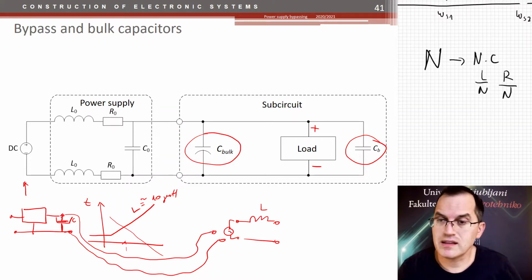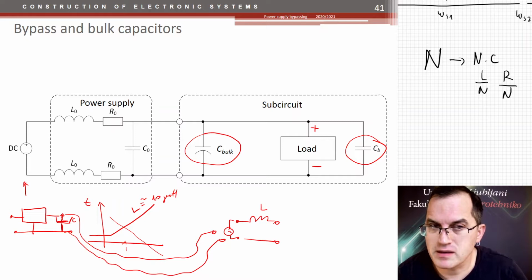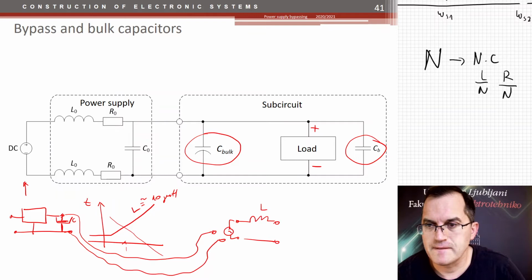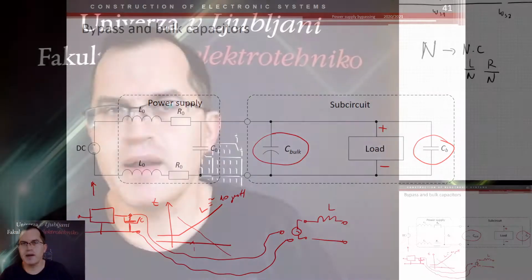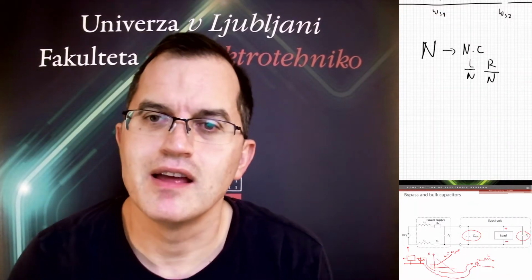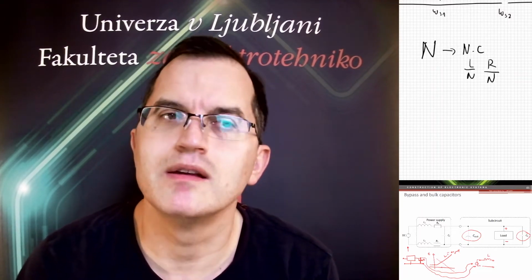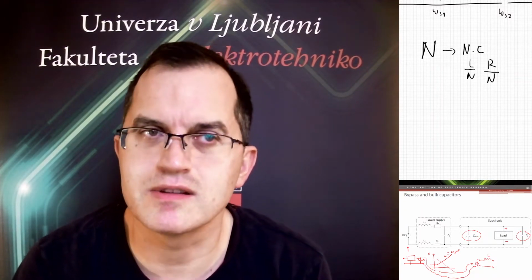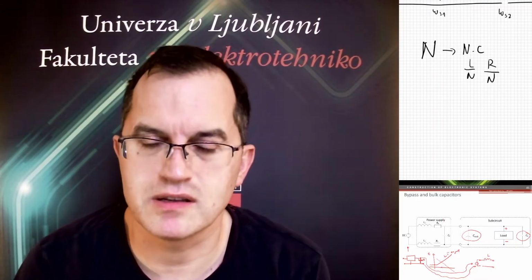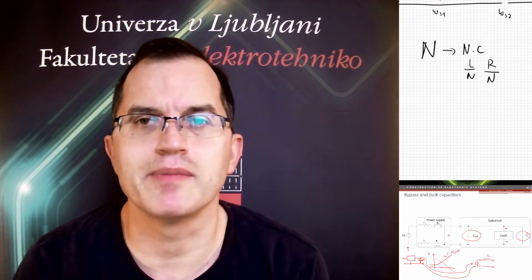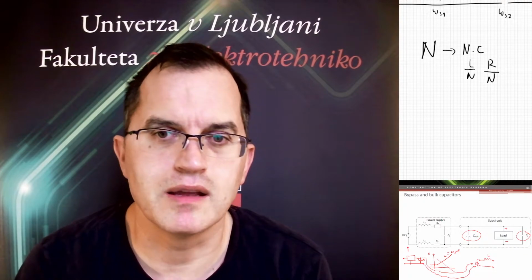And with that, I would like to conclude, because what I wanted to say is having a bad capacitor in your design is quite beneficial, because it would also provide the resonance damping, especially the parallel resonance damping, which would be your pain.